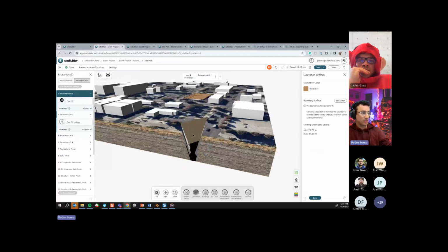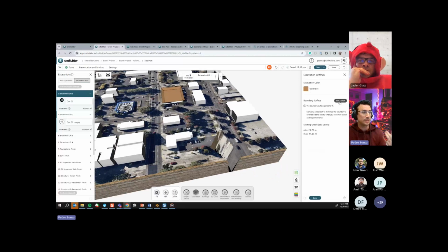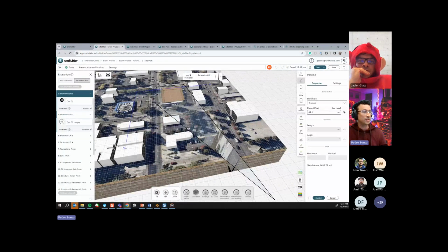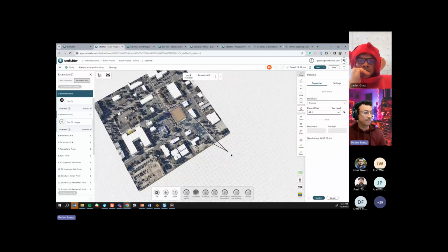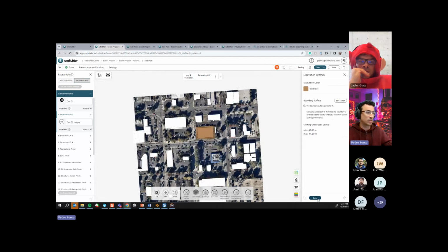And you will see this kind of broken geometry, right? So to fix that, it's super easy. Go into the boundary surface and make sure that every point of that boundary surface is inside your map. Usually what I do is I just make the boundary very big because I don't want to have to worry about that whatsoever.